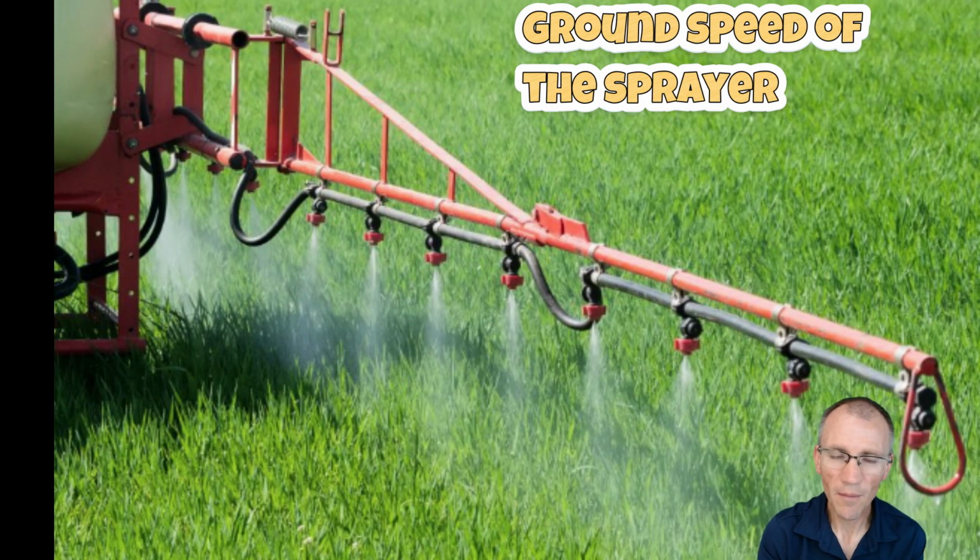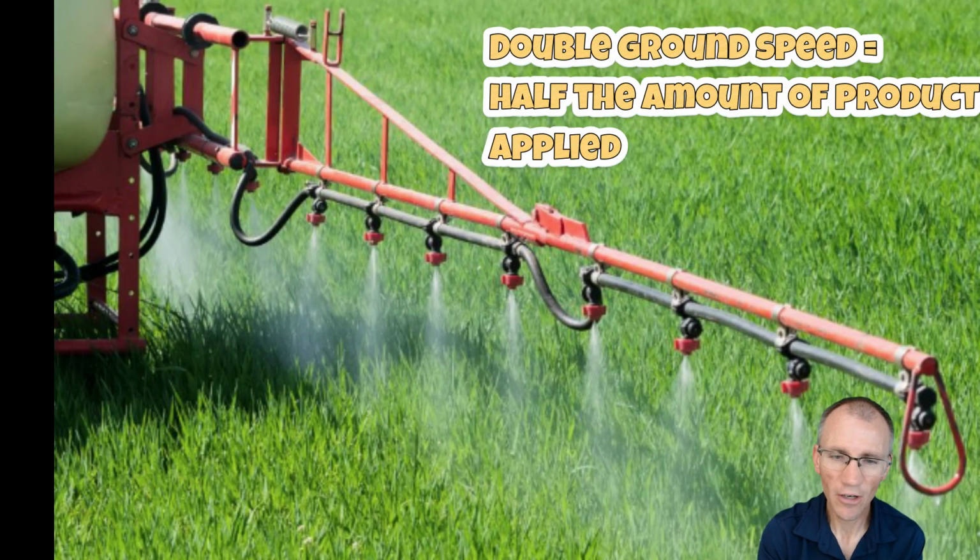If we're moving 1 mile an hour or 2 miles an hour or 3 miles an hour, whatever the case is, if we start moving faster, we're going to be putting out less. We talked about that down here at the bottom of our last slide. Obviously, if we double our ground speed, the sprayer reduces the number of gallons applied per acre by 1/2.